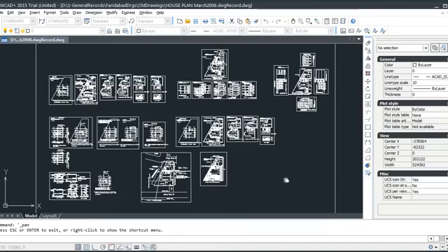It's better, because compaction is immediate action on soil or backfill or whatever you compact. We test that and we see what the density is. We achieve field density, field dry density, that is ensured to be within limits of what sample is submitted and what the results of that sample are, and that's called proctor density.